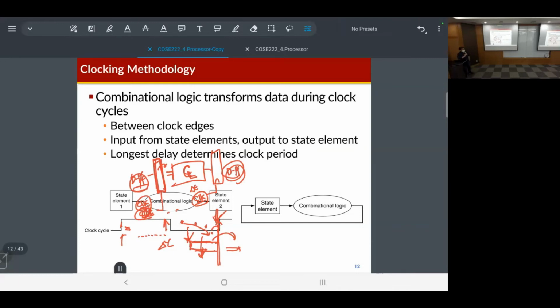Actually, this is the basic design of the pipeline. So with this D flip-flop, we just make the combinational logic. The output of the combinational logic is sampled at the same time. Okay. So then you can make a safe and stable system with this complete D flip-flop. And this type of logic is called sequential logic.